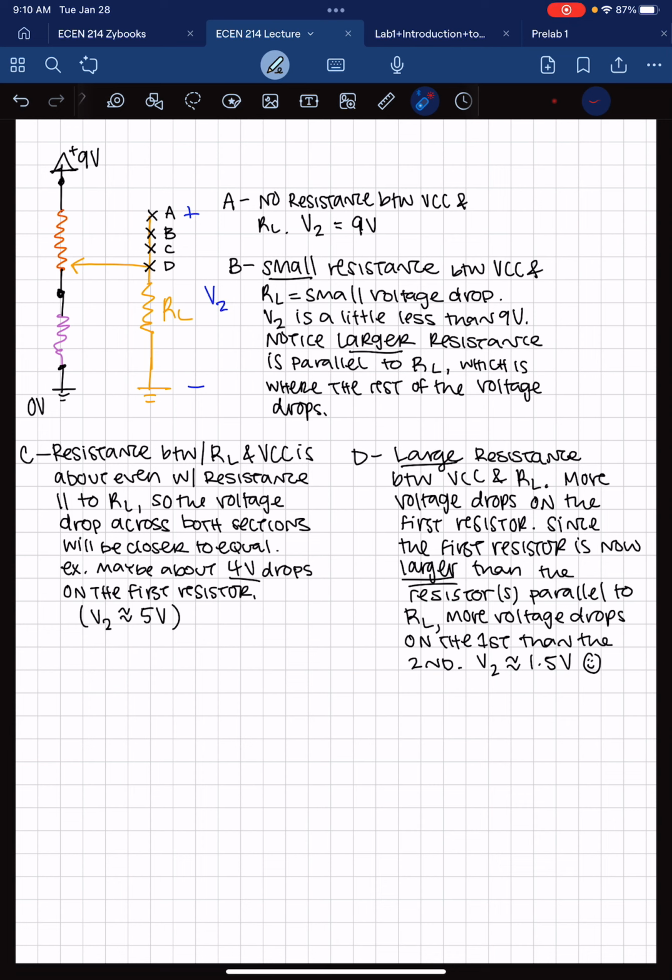So I think the whole idea that we were probably missing was, when you change your potentiometer, you literally change how much resistance is where in your circuit, and you change the current coming out of the battery, which will change how much the voltage drops on each section. So yeah, I think that about explains it.